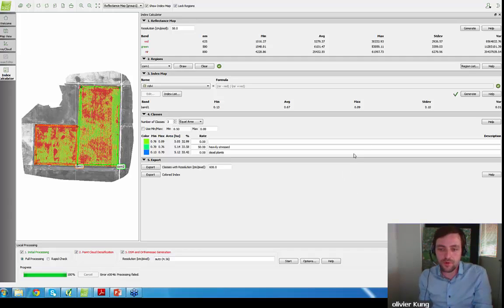Okay, a question about calibration when flying under scattered clouding. So the clouds are not an issue by themselves, as long as you can measure the effects of the illumination on the different parts of the spectrum. Basically, when you're doing it under scattered clouding, the most important thing is to use the calibration target. The radiometric calibration target is going to compensate for the effects of the lighting that's done by the scattered clouds.